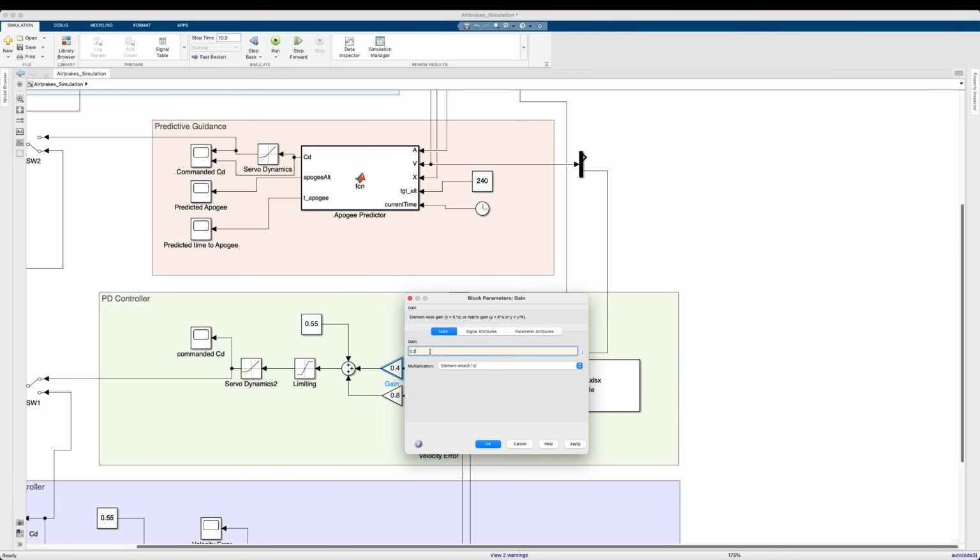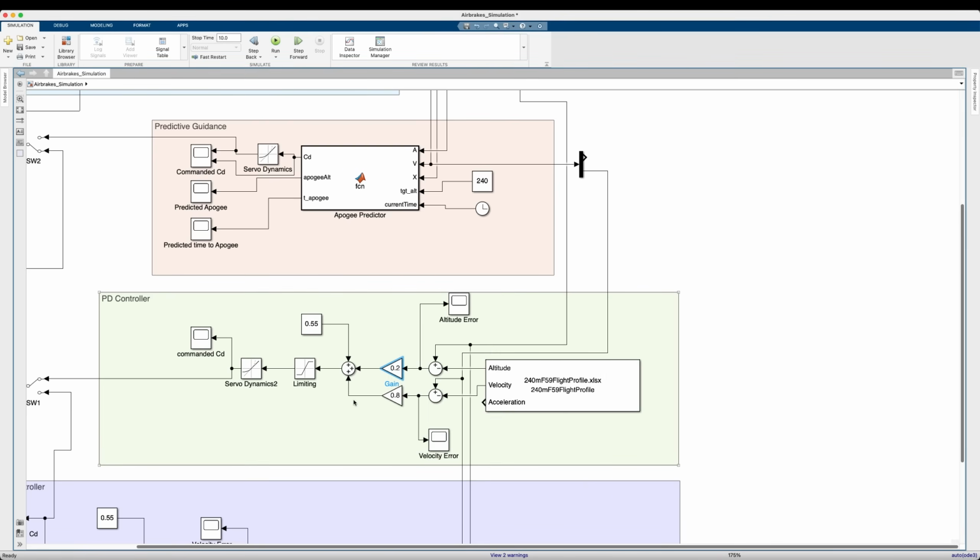Now again, this is a simulation. Simulations are models. All models are wrong, but some models are useful. In this case, doing a lot of gain tuning in MATLAB might help, but at a certain point it won't be super helpful because the MATLAB simulation behaves differently than our rocket in real flight. Our goal with the simulation is not to build a perfect representation of the physics of the real world. Our goal is to build a simulation that's close enough and gets us control gains that get us in the ballpark. Flight testing will narrow those control gains down and get our rocket to behave perfectly every time.